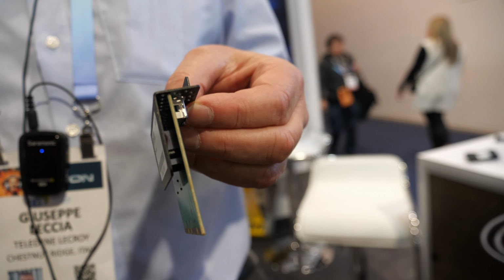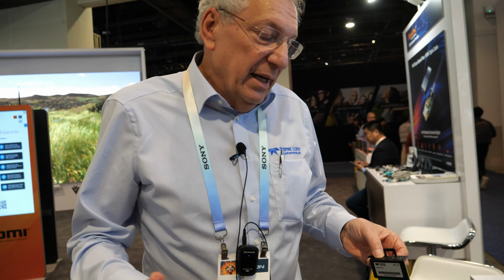Basically for two reasons. One, to change the technology, because here we have HDMI, but it can also be USB. The second one is because there is a number of insertions after which you can break the connector. For USB it's 10,000 insertions, for HDMI it can be similar. So after a while, testing millions of cables, you need to consider changing the adapter. So this is also an architecture that has been thought through from the beginning for this test tool.